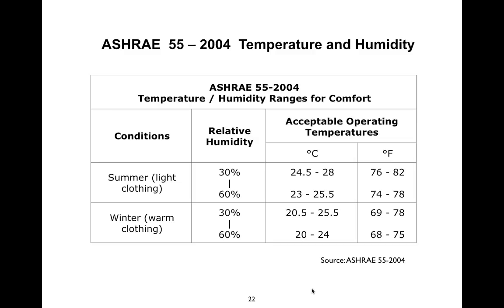Okay, so dry air is an issue, and like I said, most office buildings don't bother to humidify because it takes a lot of energy, except in certain circumstances. And those circumstances are typically if they have a data center, because electronic equipment is very sensitive to static, and static is more of a problem in dry air.